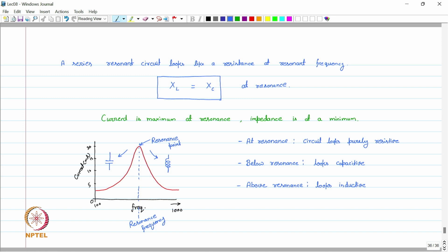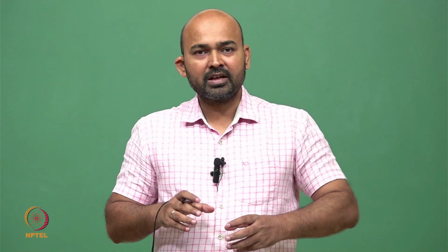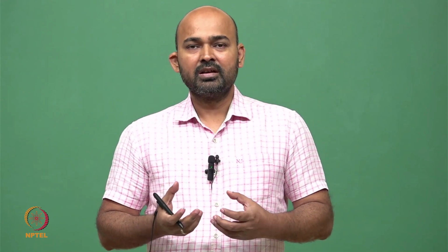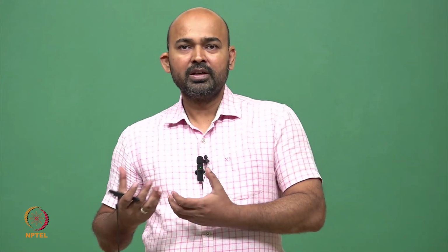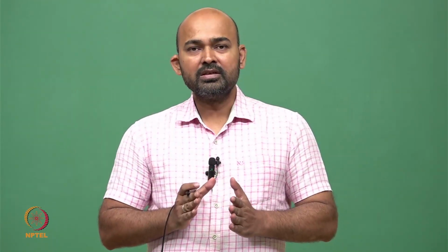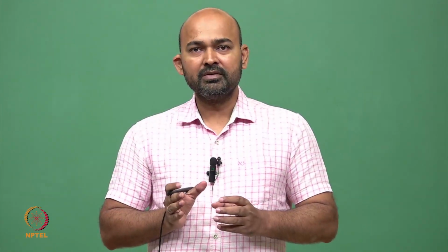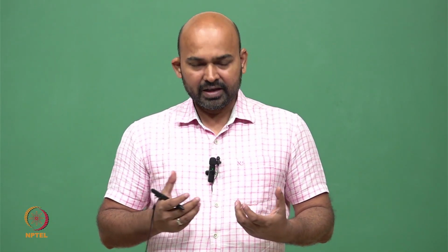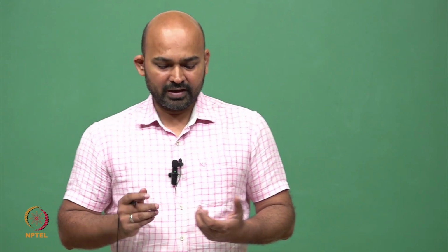So here we see that at the resonant frequency the circuit behavior actually changes from capacitive to inductive behavior, and at resonance the circuit is purely resistive. It means there is no inductive or capacitive effect. These effects can be easily detected by external circuits.